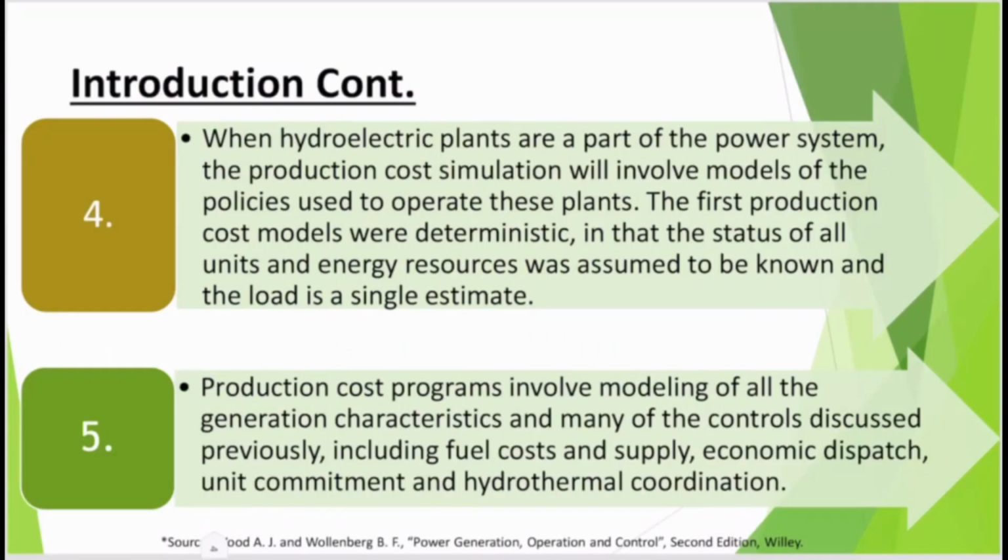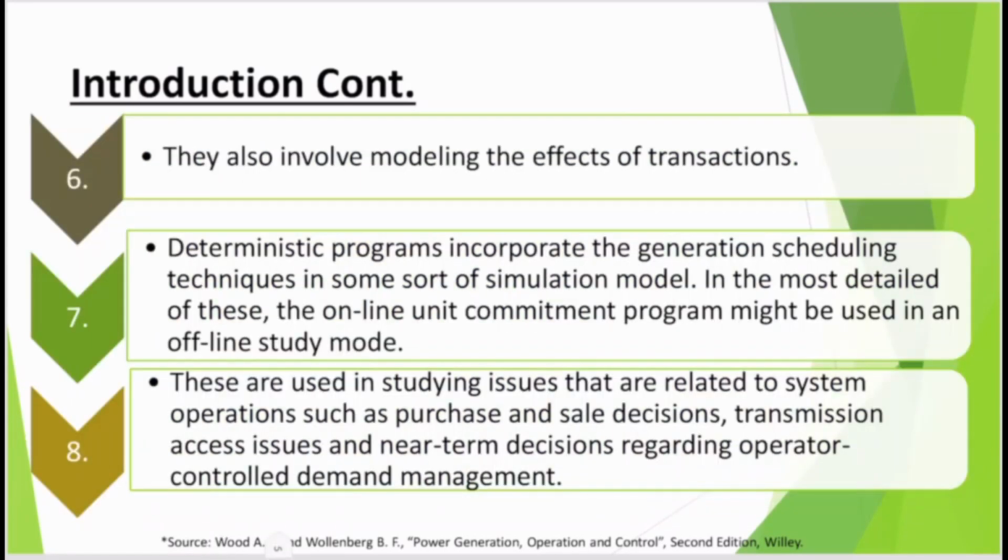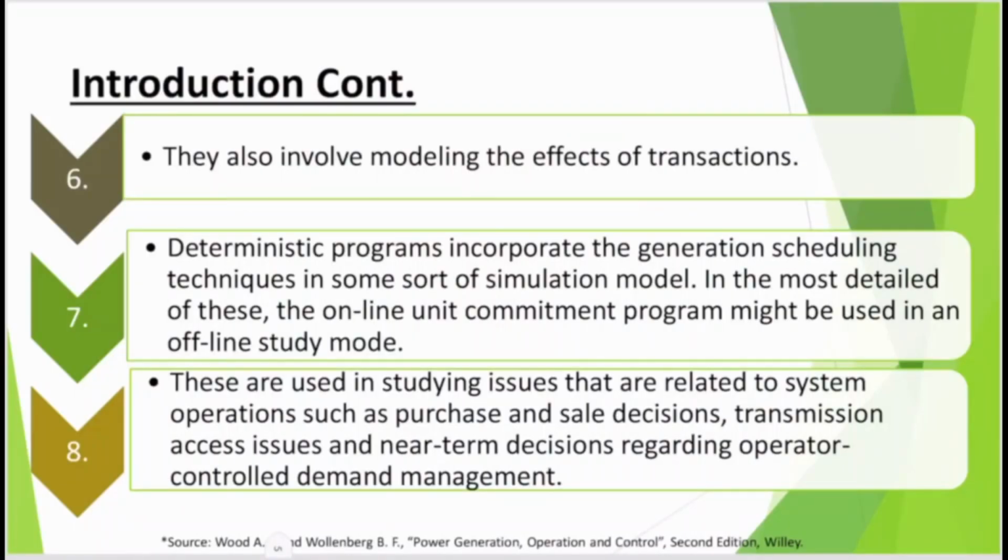Now, the production cost programs involve modeling of all the generation characteristics and many of the controls discussed previously, including fuel cost and supply, economic dispatch, unit commitment, as well as hydrothermal coordination. They also involve modeling effects of transactions. Deterministic programs incorporate the generation scheduling techniques in some sort of simulation models. In the most detail of this, the online unit commitment program might be used in an offline study mode.